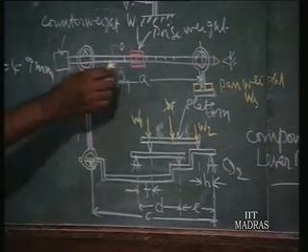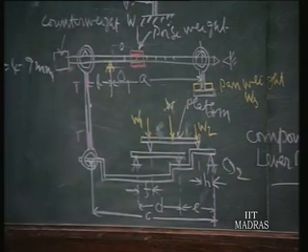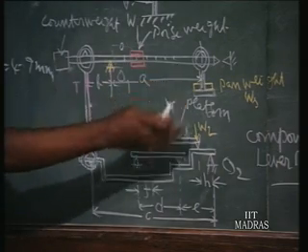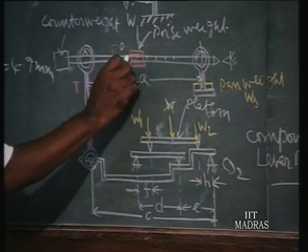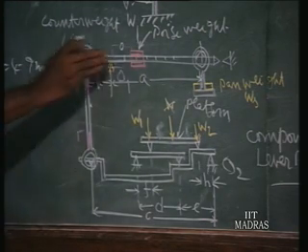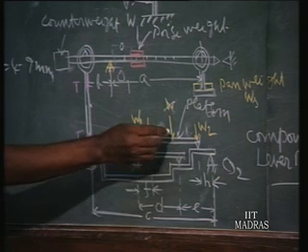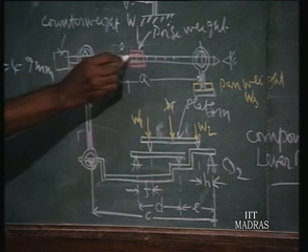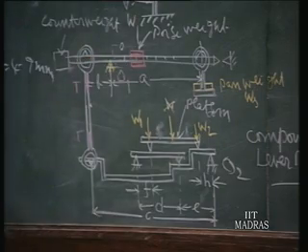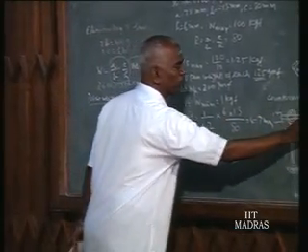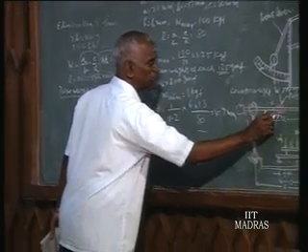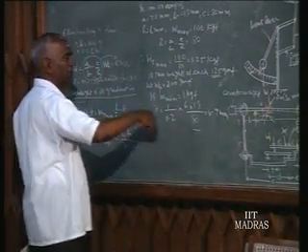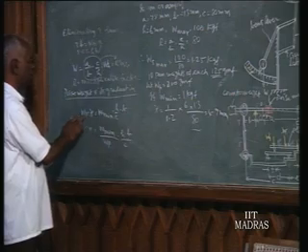Now we have pan weights for every 10 kilogram. Between 10 kilograms, say 1, 2, 3, 4 or 11, 12, if you want to measure, we should have a reading here for 1 kilogram force. For that purpose, let us assume a weight of 1 kilogram force here, that is W minimum as 1 kilogram force. What should be the poise weight here, that we have to find out. Assuming a distance x is moved, the poise weight being WP, we move by a distance x for the next graduation. Then the additional moment is WP into x.